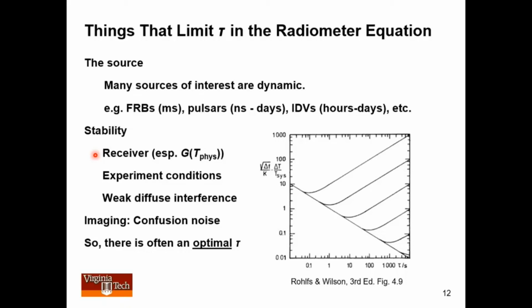And that becomes now something which confuses the measurement. So a picture that would be helpful here is to look at essentially signal to noise ratio as a function of time. It's log, so it goes down by this factor of 1/2, corresponding to the square root of b tau. In principle, you should be able to ride this curve down for as long as you want. And every once in a while, people can do this. They can get very, very far down here.